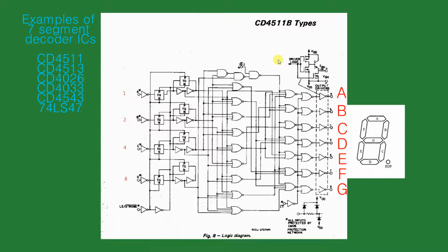Okay, so how do we convert the binary in our circuit, whatever we're using to drive this IC, say a microprocessor? How do we take the binary output from that circuit and create the 7 segments that we need to drive the display? We need a 7-segment decoder driver like the 4511. You can see a more detailed description of this in one of the other videos I've made. So with this circuit, which is very nicely provided to us by the engineers at Texas Instruments, for example, this looks like circuit spaghetti here, but we don't have to worry about that because it's internal to the chip.